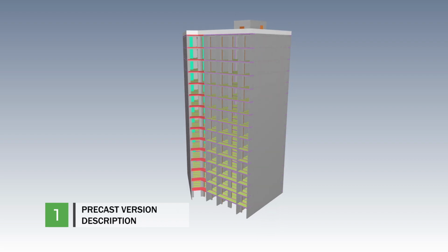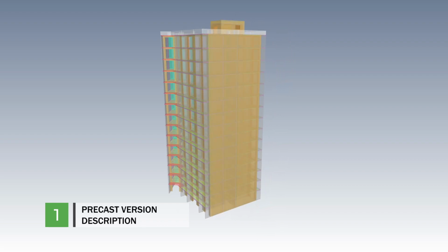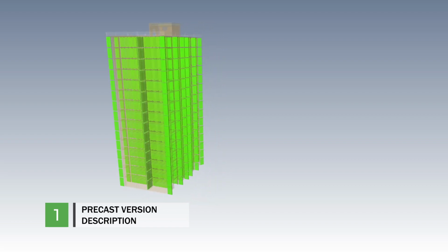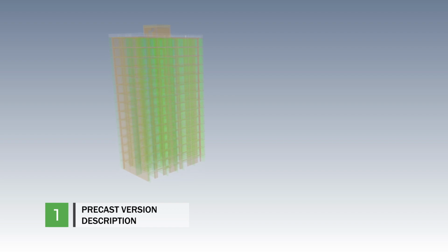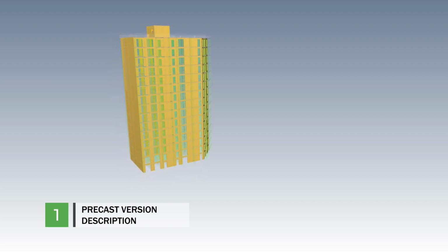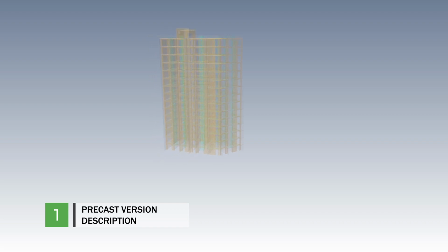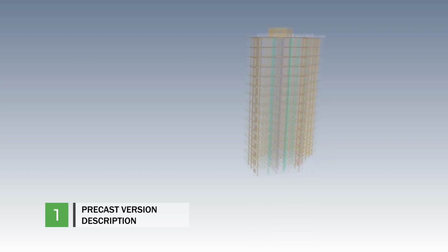The precast reinforced concrete frame is made of concrete C20/25 and consists of interior walls made of single-layer panels 200 mm thick, external walls made of 3-layer panels 305 mm thick, as well as precast hollow core pre-stressed reinforced concrete slabs 220 mm thick, and cast-in-place parts for the floor slabs.